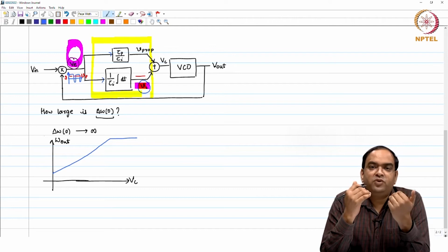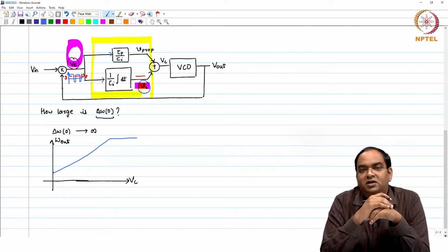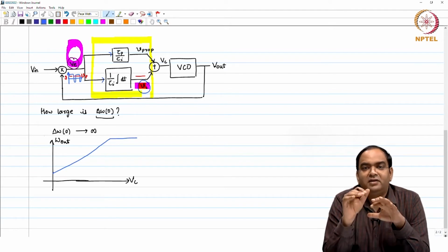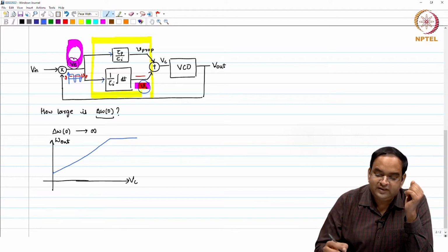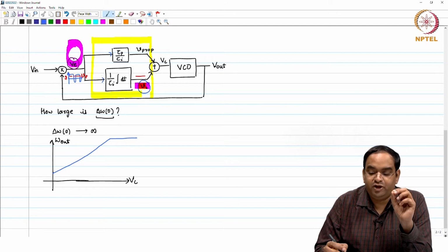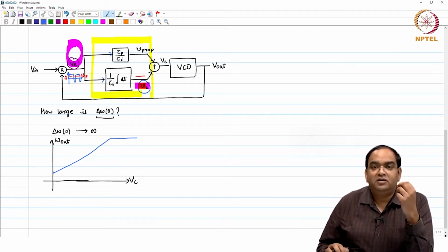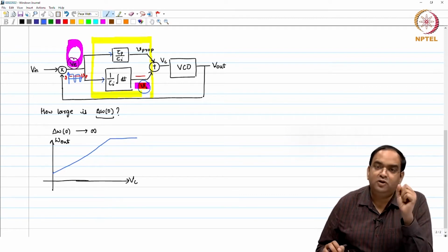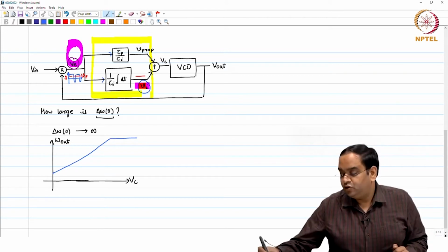You know that you cannot increase the voltage beyond a certain value in a given CMOS or BiCMOS technology. So, your frequency is always going to be limited by that at least. So, this loop itself does not put any restriction on the output frequency. Mostly the output frequency restrictions are added by the VCO or some other block, maybe the loop filter or any other block.